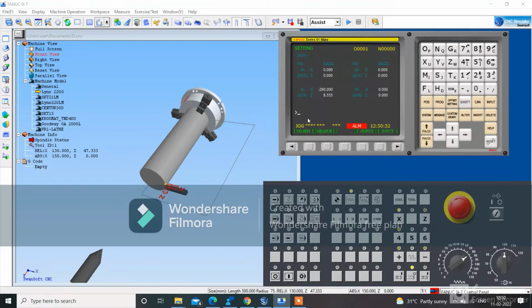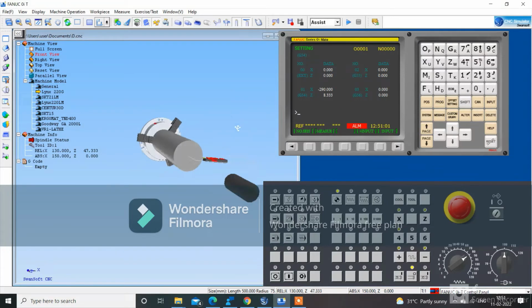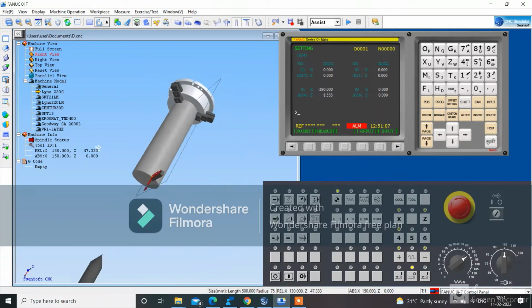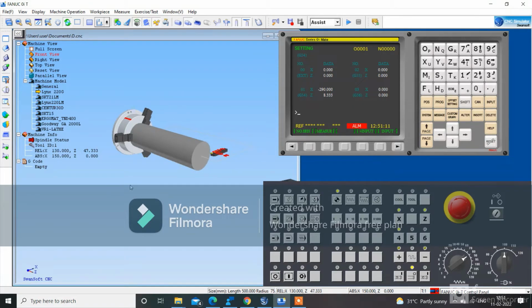This is completed. So the next process, as you expect, we have to go for the reference coordinate key. Reference coordination plane is indicated by this key. So I go for it. Now you can see X and Z here is blinking. So now there will be a particular relative movement between this workpiece and the tool. So I keep it like this.